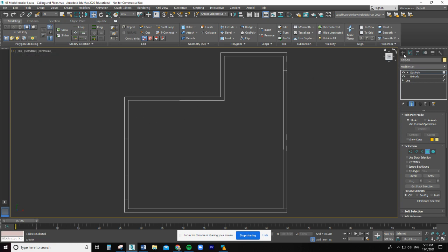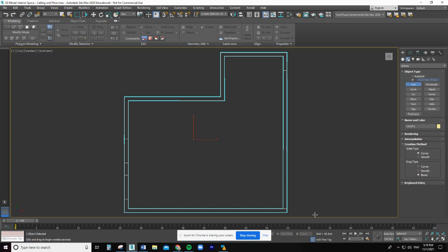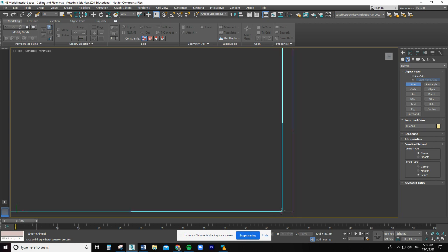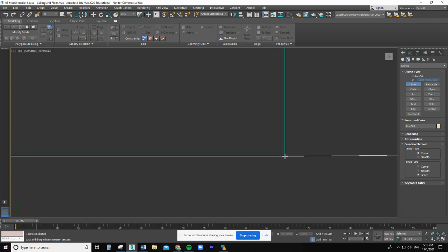And now let's do a new shape here. I'm going to go to my Create tab, under shapes. What we want to do now is draw a ceiling by reselecting kind of the original wall set that we used to draw the walls and extrude the walls. So we're going to go back into line. There's a bunch of different ways to do this. We can do it with rectangles, but out of all the ways that I've tried and experimented with, I think this is the easiest. I'm going to start here for the ceiling.